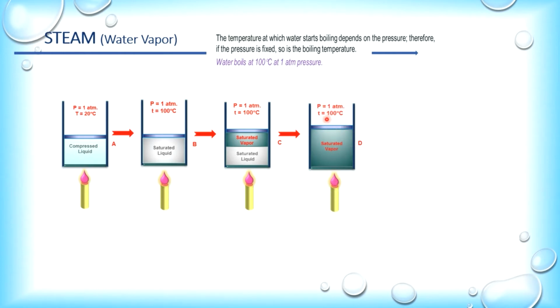The temperature now will not remain at 100 at this stage where every single drop of liquid has been converted to vapor. So at this stage, if we supply more heat at constant pressure, this will now undergo a change in temperature, maybe to 120, maybe to 101, or to any other temperature higher than its boiling temperature or its saturation temperature.